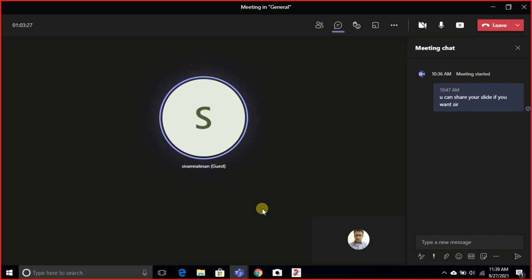It can either be configured as input or output. IO cells 1, 2, 3 and 4 can also be configured as either input or output, but they have separate pins. But in IO cells 5, 6 and 7, they share the same pins.